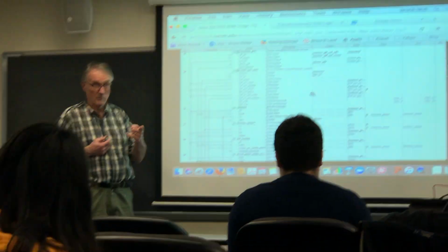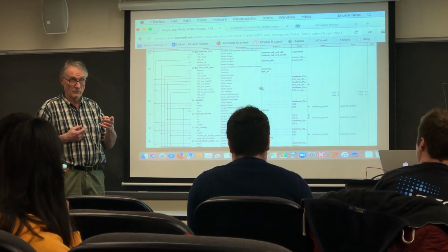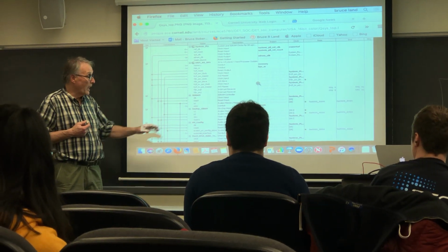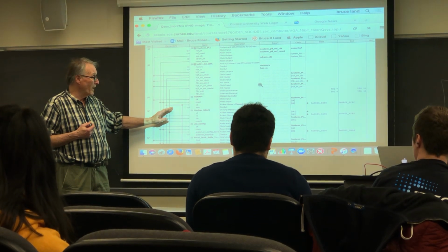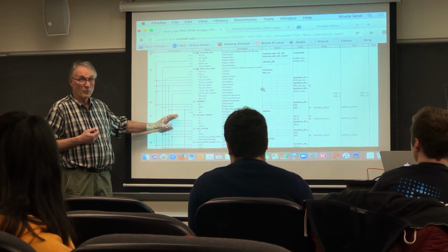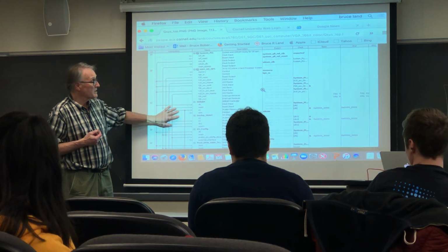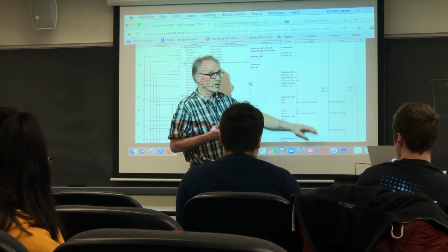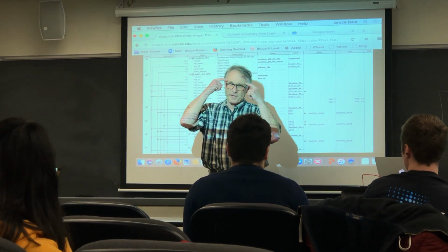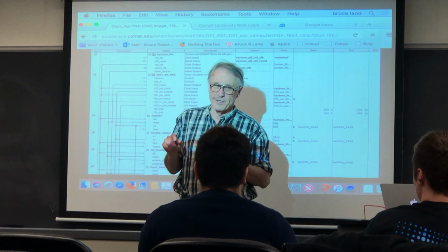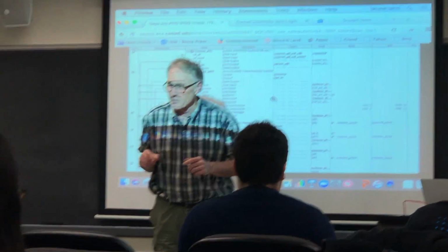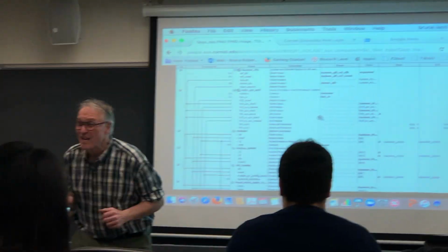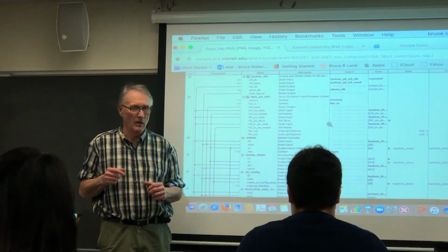So is everything we do for the Qsys clicking buttons on this? Or do we actually write something? Everything you do with Qsys, you do by this WYSIWYG, point-and-shoot interface that wires stuff up. You type in fields here to change addresses. There is an auto address feature. You click it, and it will guarantee that there are no overlapping addresses. That's cool. Downside is it changes every address, and so you get to change your C code.